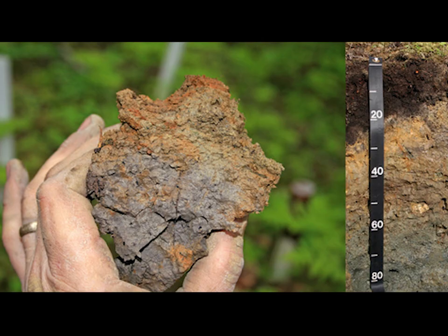When designing a septic system, you need to have core samples of the soil, looking for redoximorphic features, commonly referred to as redox features. These are color patterns formed in the soil by the process of reduction, translocation, and oxidation of iron or manganese compounds.